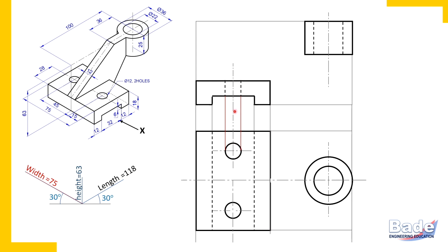So two major parts are over, and connecting these two major parts there is a thin plate of thickness 12 millimeters. So its larger surface appears in the front view, and in the top view the plate appears only a strip of thickness 12 millimeters. Of course this strip must be drawn in the top view between the end projectors, but its largest surface, that is shape of the plate, whatever it is, this shape appears in the front view.